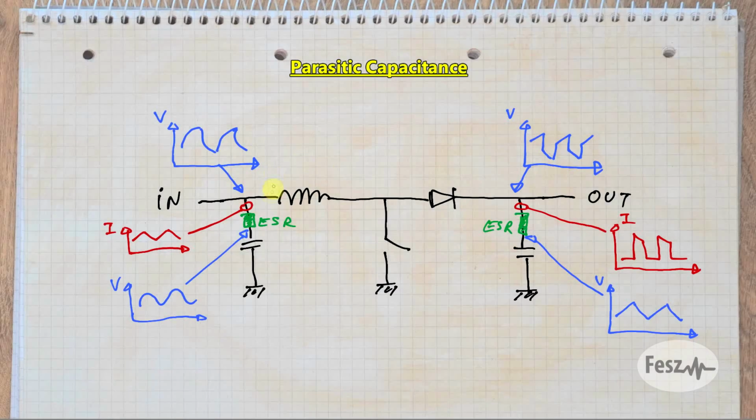So the parasitic element that is missing from our analysis is the parasitic capacitance of the inductor and the diode. It's usually just a few picofarads in the inductor, but the diode can have quite a lot. And this will also be coupled with some other non-ideal effects. Anyway, the result of this is that the high frequency part of the noise, present in the sharp transitions of the switching node, has a way of directly exiting the converter. Now, normally the capacitor would filter this, to some extent at least, but it doesn't do that completely. Some of the noise still makes it through.